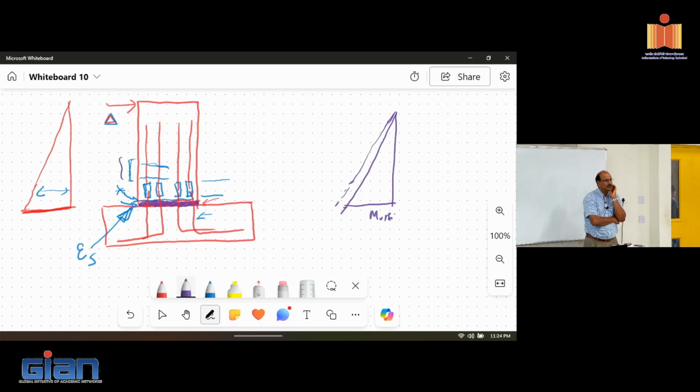Sometimes even the location is not considered. They will locally bend the bars to go there. I have a lot of pictures from our own projects. That's what I keep telling: the reason we do precast is to improve quality, not to bend bars in the field. The dowels, to facilitate even transportation, are bent, and the larger the diameter, the more you bend it, it fractures. We were not sure what to do. We cannot reject so many elements.